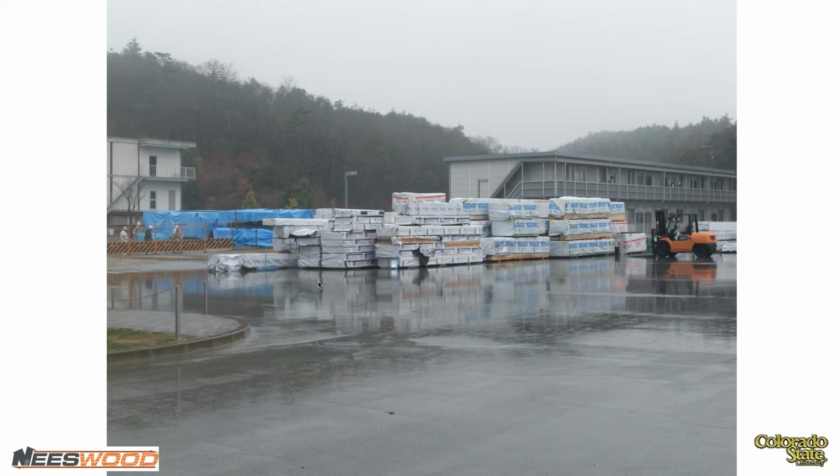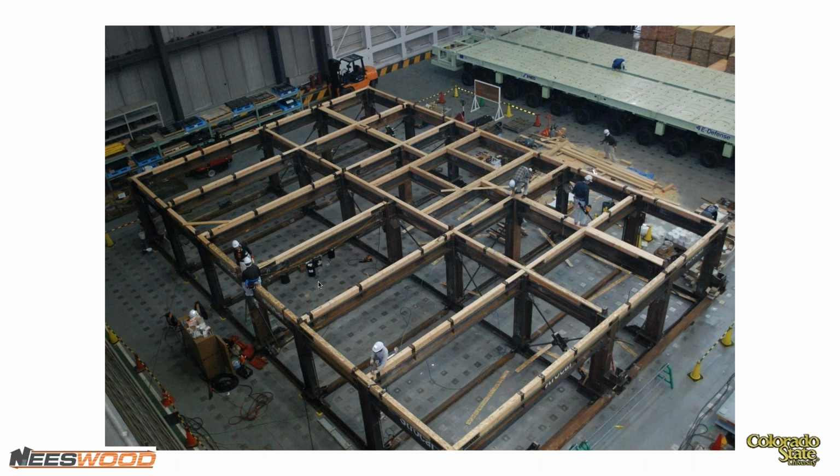Okay, so to start this off, we shipped 20 full-size 40-foot shipping containers out of 3 ports in the US and Canada with North American lumber, steel for the base, as well as hardware. And here you can see the steel going in. And so this base frame was designed by colleague Steve Pryor at Simpson Strong-Tie, and it actually served as the lifting frame, so a space truss to lift this onto the shake table. But it was also then part of a different phase of testing as well.